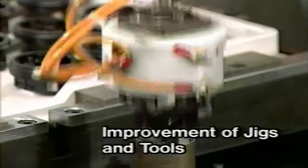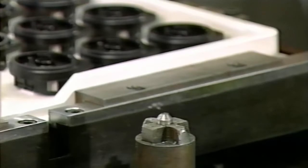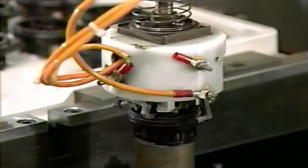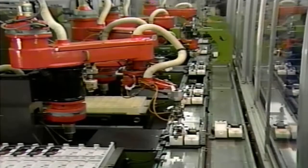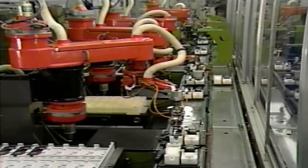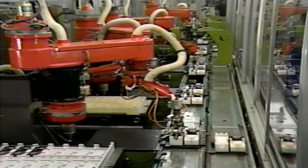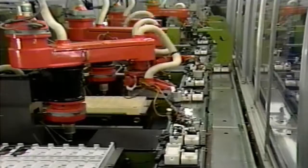The second method of approach is to improve the design of jigs and tools. Of course, you must understand the design weak points clearly before you can improve anything. First, you check each item to see if the alignment and positioning of the equipment or the shape of the jigs needs to be changed, and whether the jigs, tools and components of the machines are really useful or not in terms of materials used and functions. Then you can make a counterplan.